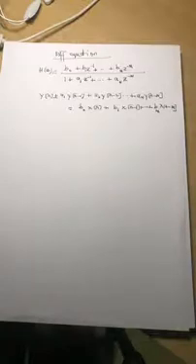So we are discussing something very important, that is about the whole reason of performing Z transform. As I mentioned earlier, the whole purpose of performing Z transform is to find out about the stability of the system. Stability of an IIR system. We never worry about the stability of an FIR system. An IIR system is usually represented with a difference equation.